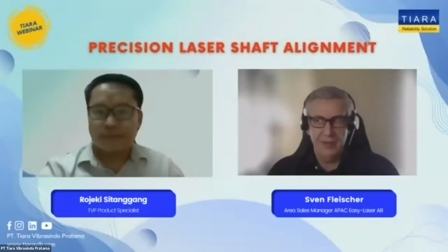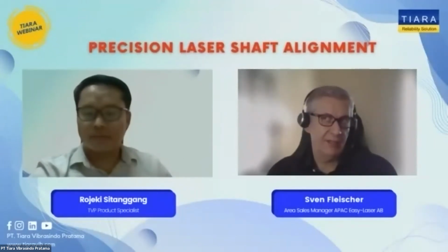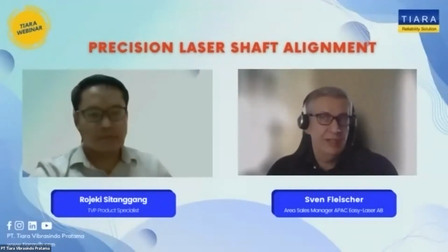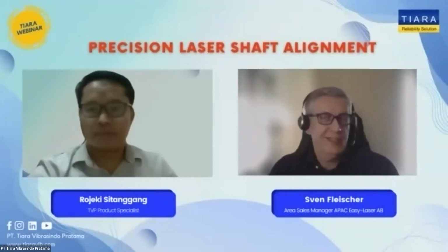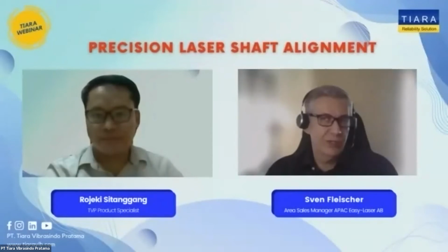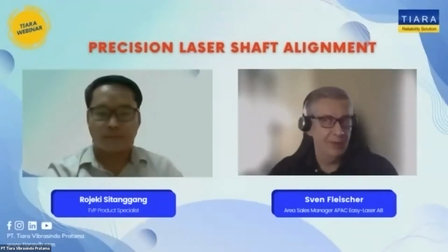But distance could mean shaft alignment, but also more. We have additional lasers and detectors that can measure with the same accuracy up to 100 or 200 meters. That applies potentially to flatness. That is of course something a little bit extraordinary, and not everybody uses it. But if it is required, you can just add another laser, which is more consistent over distance, to achieve hundreds of meters, depending on the application, in cranes for example, or in roller parallelism alignment.